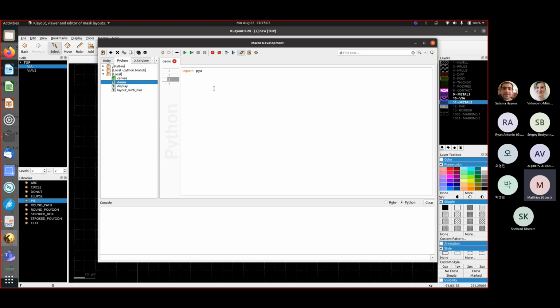My recommendation is always, if you use Linux, then you can essentially import or pip install every other module, every other package you want to have, like NumPy, SciPy, whatever. And then you can easily use it inside KLayout because it shares the system Python. It's even more messy on Mac, because on Mac there's Homebrew, there's Anaconda, there's I don't know how many, there's a system Python, so people never know what program accesses what, and it's a kind of mess. I would prefer having that in Anaconda, and I would even prefer more to have KLayout as a package in Anaconda, but I didn't manage to convince them yet to include it.